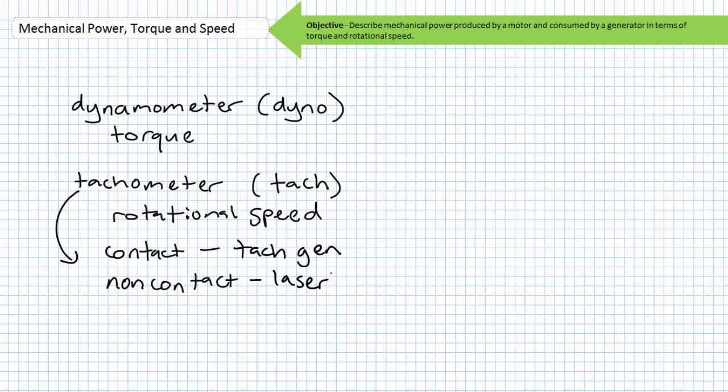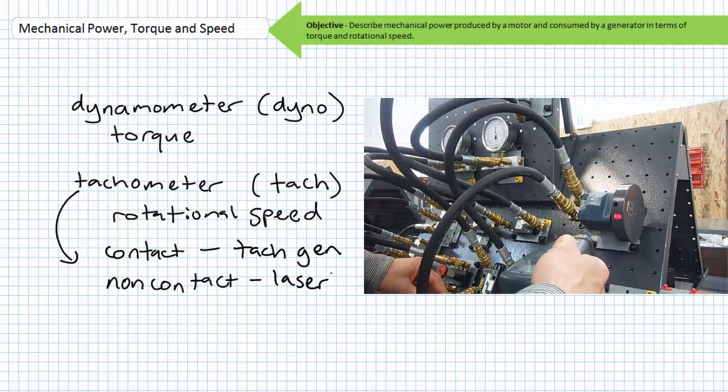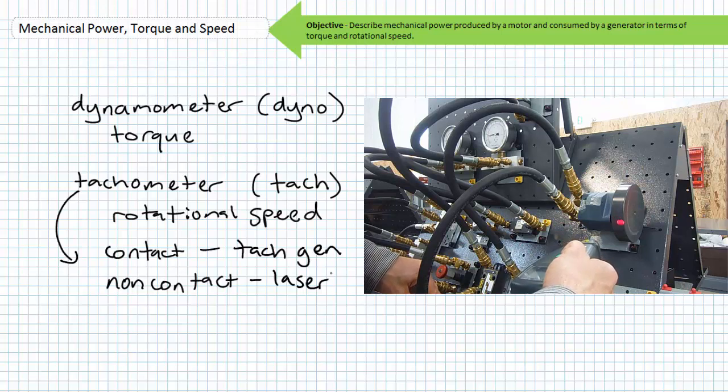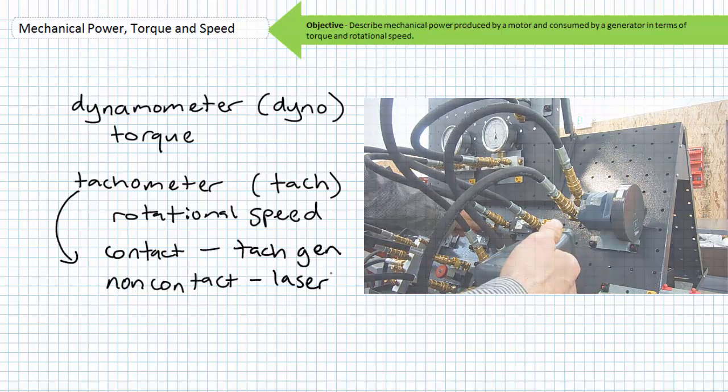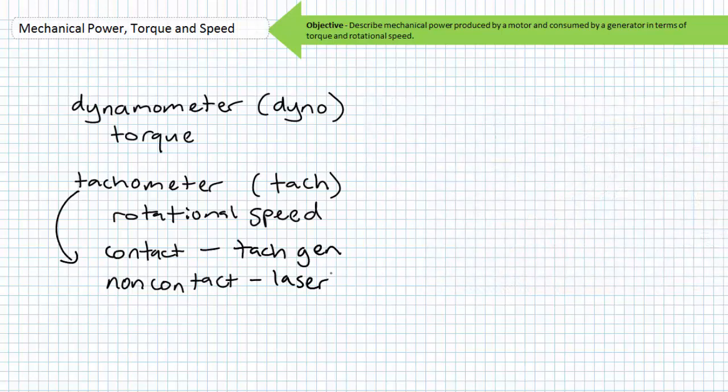A handheld laser tachometer can be used to measure the speed of a rotating mechanical object. In this case, a hydraulic motor. This is a retroreflective laser tach because it requires a piece of glint tape on the motor shaft to return the transmitted laser light back to the receiver. This is obviously not the preferred method for measuring a shiny metal object. In that case, you might need to use a polarized retroreflective scanner. The laser tach can't be held too close nor too far away if you want accurate results.